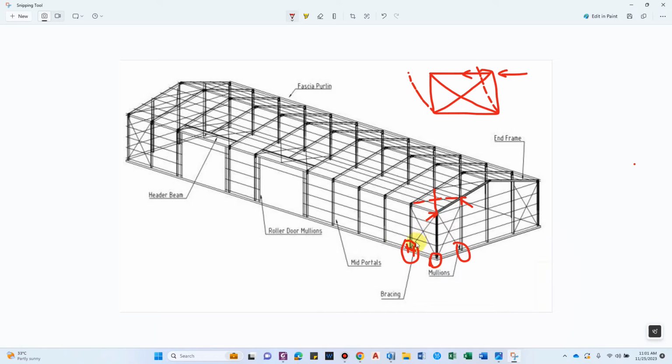And also if we see the plan view for this wall, if we see this frame, we have bracing here, right? And when we have an axial force, that goes in this direction, and this bracing goes into tension or compression, whatever. That depends upon the type of section you provide here, whether it is a strap, a rod, a hollow section, or an angle section.